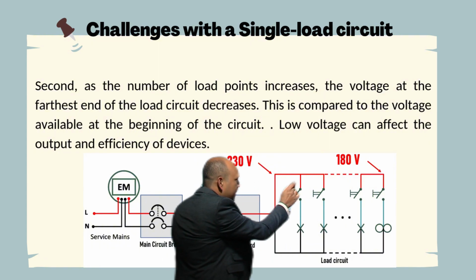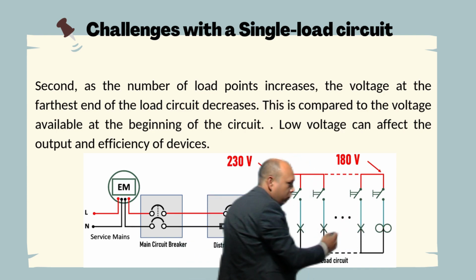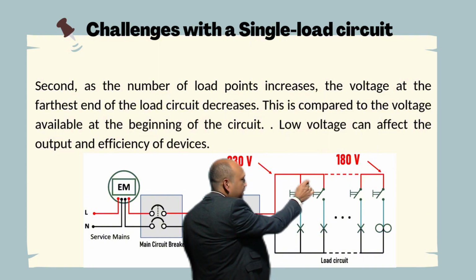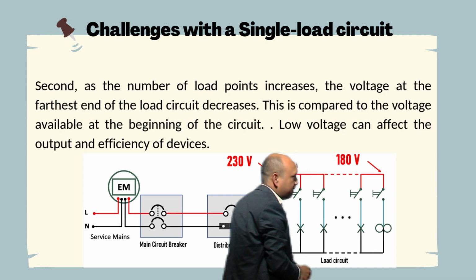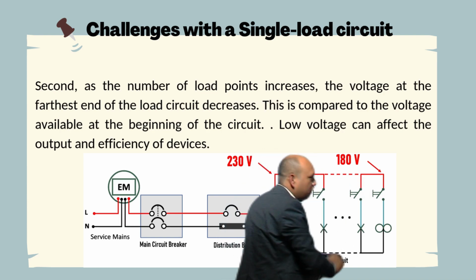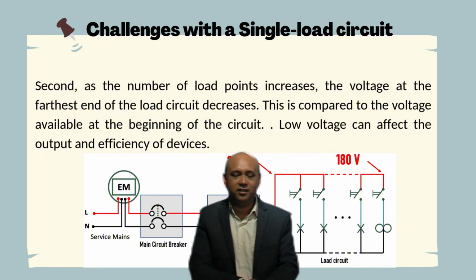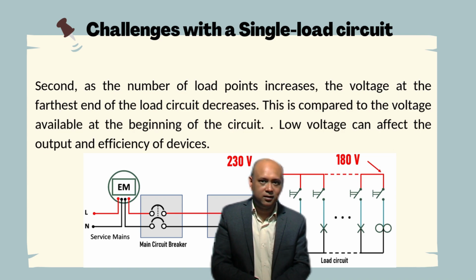So whatever voltage we are going to get here, if the number of loads is very high, then the voltage difference between the beginning of the circuit and the furthest point of the circuit will be very high. So this low voltage can affect the output and efficiency of the devices.